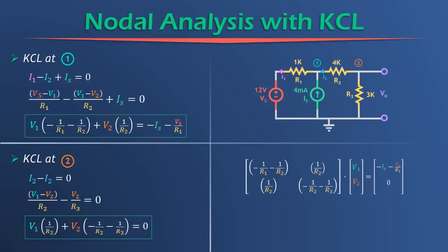And then, however you want to solve for this is up to you. You can use system of equations, you can plug things in. Whatever is most comfortable for you is what you should use. For me, I can pump this into my calculator pretty easily, so that's probably what I'll do. I would do the inverse of this matrix times this matrix, and that should give me V1 and V2 pretty easily. Before I get ahead of myself here, we can rewrite this matrix with real numbers. So I've converted all the R1s, R2s and R3s into real numbers here, and I've converted this expression into a real number over here. And so I can solve for it.